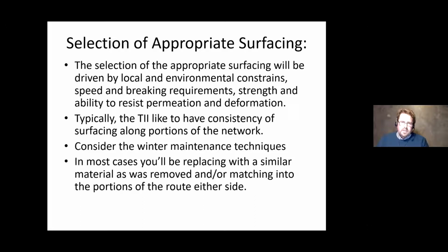Both for maintenance, constructability, but also for your winter maintenance techniques. So you need to be conscious that your gritters need slightly different setups for different types of surfacing. So be conscious of that when you're moving forward. And just generally, from constructability and practicalities, you want to try and keep it to the similar kind of style and material as you have there already, just because drivers get very, very familiar with what they're used to.